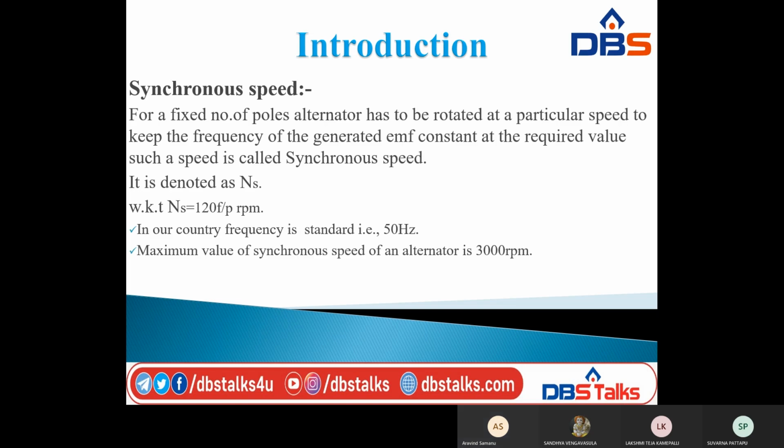Next in the introduction is synchronous speed. For a fixed number of poles, an alternator has to be rotated at a particular speed. If we take 2 poles, we have to use 2 poles only; if you want to use 4 poles, we have to use 4 poles. So for a fixed number of poles, the alternator has to be rotated at a particular speed to keep the frequency of the generated EMF constant at the required value. Such a speed is called synchronous speed.